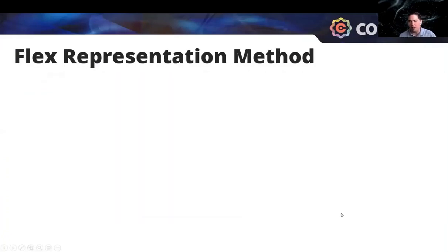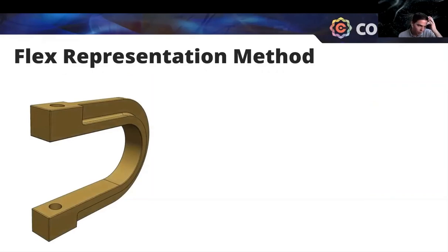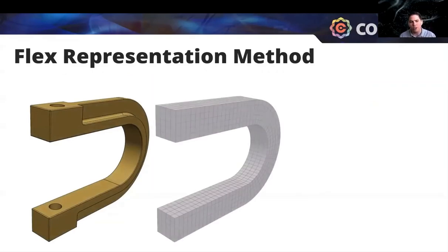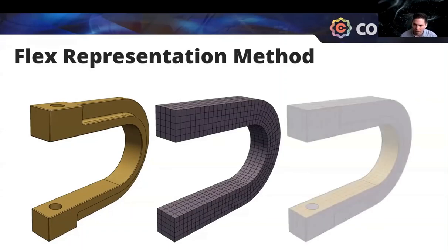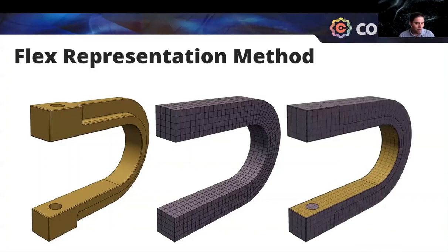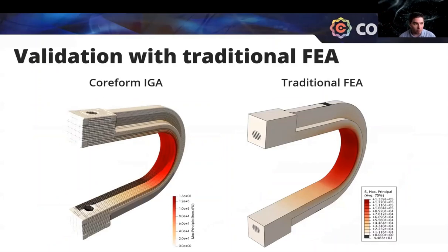So then just to recap what we did in that pre-processing, we took some physical domain without defeaturing. We immersed it in this computational domain, this background grid, so that we immerse the fine features of the model, and we'll recover those through adaptivity, adaptive quadrature, local refinement of U-splines. But then we've generally captured the general shape of the part, which allows us to have higher accuracy per degree of freedom than if we had immersed this in a single large bounding box. And then validate this against traditional FEA.